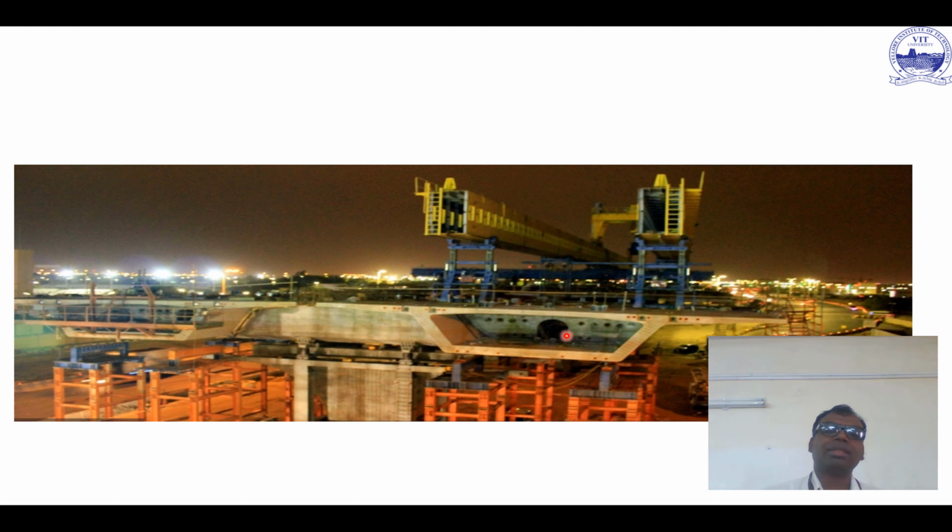Usually the diaphragm is placed at the end, and the rest of the elements will only be hollow. These box sections are very good at resisting torsion also, which an I-beam is not really capable of. Again, if you look at the thickness of all of this, it is very, very small when compared to the size of the element.